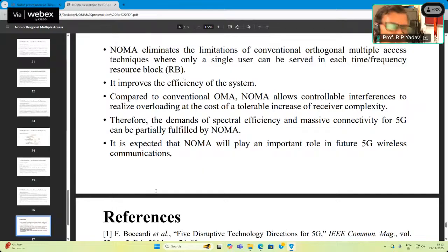So if you are operating, let's say, at 20 gigahertz or 30 gigahertz, thinking about making the instrument, how do you test them? Because when you design a system, can you design a VLSI chip for a 20 gigahertz signal, or can it operate at that? Obviously, it will not work out. So you will have to go to millimeter wave integrated circuits. Those who are familiar with MICs, microwave integrated circuits, know that for such high-frequency devices you will have to go to some new technologies.